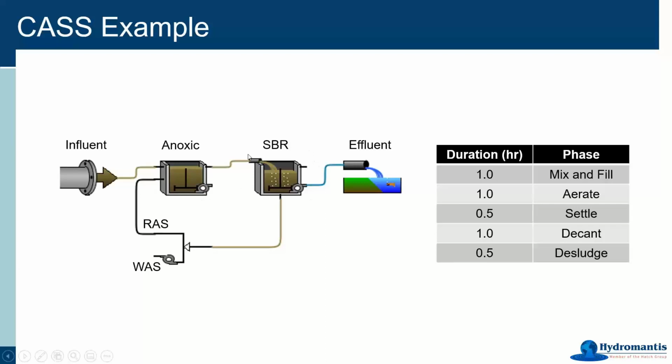Then this can actually move around and do what it needs to do in the regular setting, and this can receive a regular and continuous amount of wastewater flow into the anoxic zone and then into the aerated zone. Now, in this particular example, these CAS systems also want to be able to receive that flow continuously. And so it has multiple systems in parallel, like a repeat of what I'm showing you on this screen here, in parallel, so that they can be used out of phase with each other.